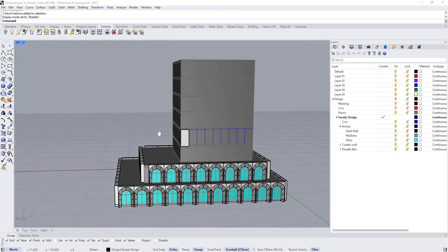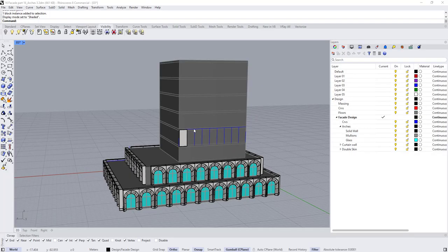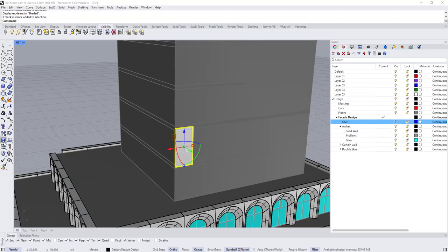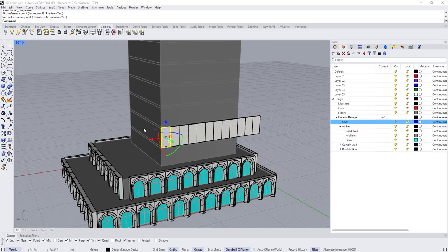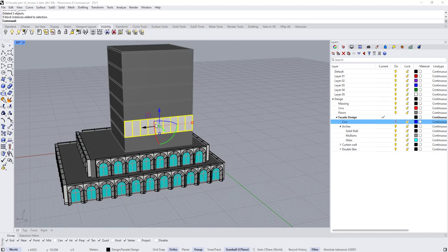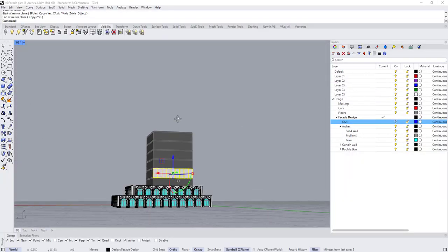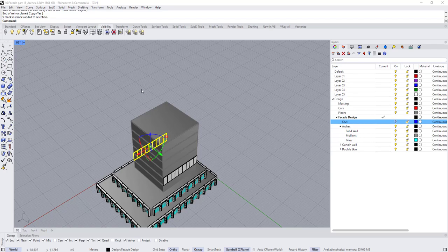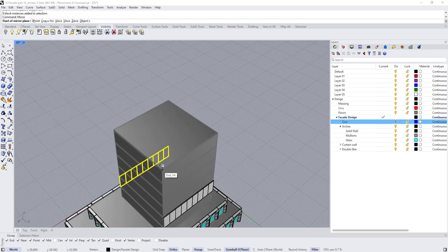So I'm going to repeat it along the whole facade, like what I did here. I think I might speed this part up to save time a little bit. And I'm going to hide the curve layer first. So you can select it, choose linear array, set the number to 12 maybe, from this point to this point, delete any extra, select this, choose mirror, and set copy to yes. Now we can select this, and maybe create a mirror.